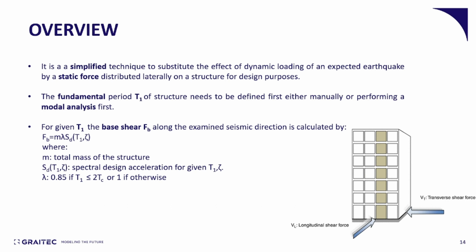Basically, instead of having all the eigenmodes and combining them, the superposition of the eigenmodes, we select the fundamental period τ1, the period that corresponds to the fundamental eigenmode of the structure.